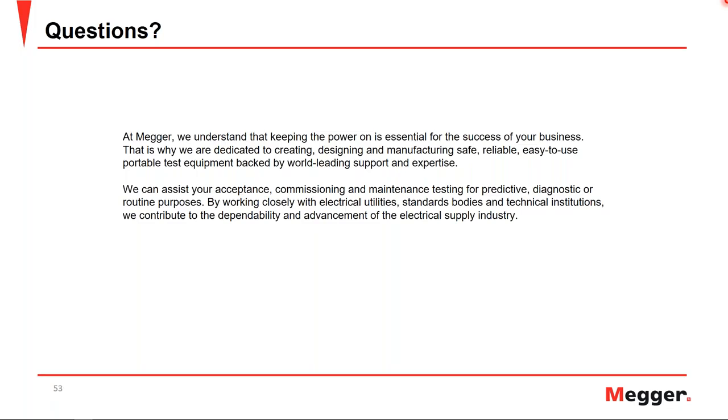Well, this is one of those questions where the answer is: it depends. It depends on the condition of the insulation. If the insulation is deteriorating fast, or if it is operating under certain conditions that might deteriorate the insulation faster, then you need to put these transformers on a special testing regime where you look more into it and get more results.